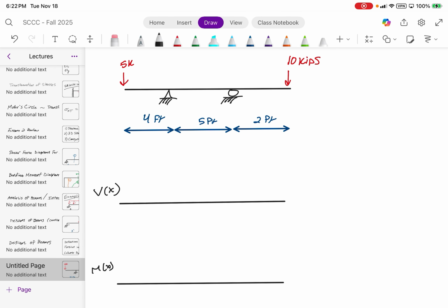You're making an assumption of the reaction. So you've got -5. The thing is, even though the force is -5 kips going downwards, it's causing a positive rotation. Don't just add the negatives and positives until after you write all of the equations, because then you can account for how they're rotating.